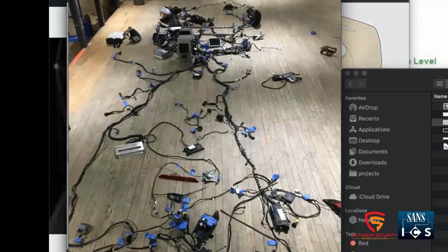There's also an important concept in the CAN protocol that helps decide which devices get priority, which is called arbitration. We obviously want the more important devices, coming back to the simplified example, the engine and transmission and brakes, to have more priority over things that are less important, for example, the radio or moving the window up and down. So this priority is mapped to arbitration IDs, and these IDs help identify which CAN messages are being sent. I'm trying to be nuanced here and not say that the arbitration IDs map to devices, because that's not quite it.